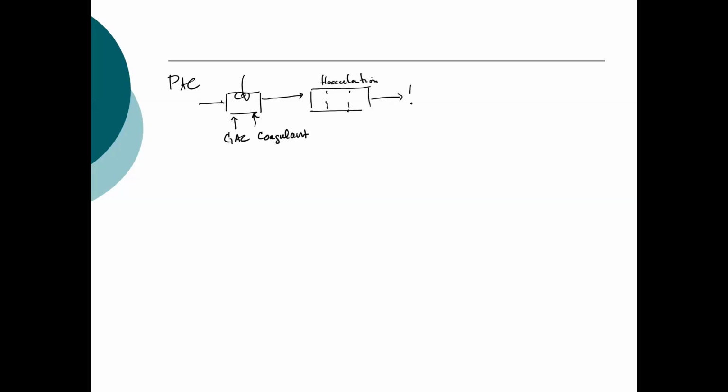But just to reiterate, we looked at a batch system, but we also looked on Friday at powdered activated carbon. So powdered activated carbon, it's kind of the consistency of powder that you would put on your body. There we added that typically to a rapid mix system. So we add PAC, we may add a coagulant, we go through flocculation, followed by sedimentation.